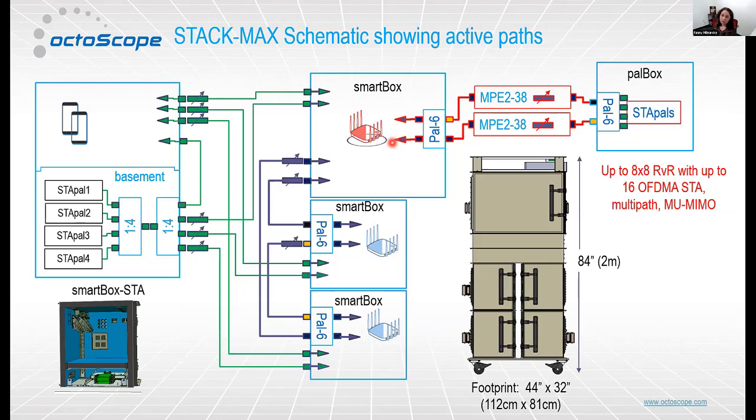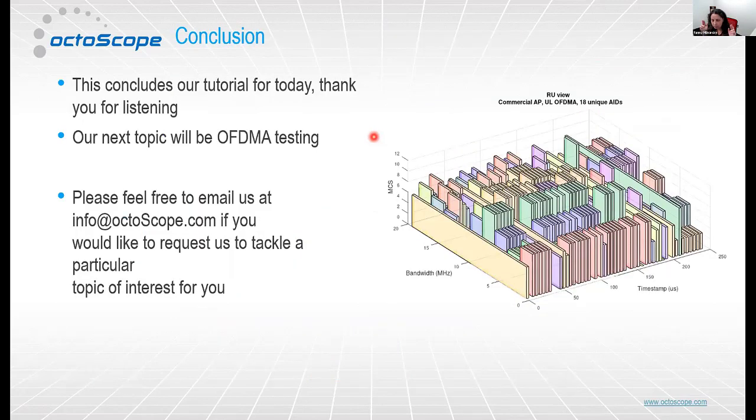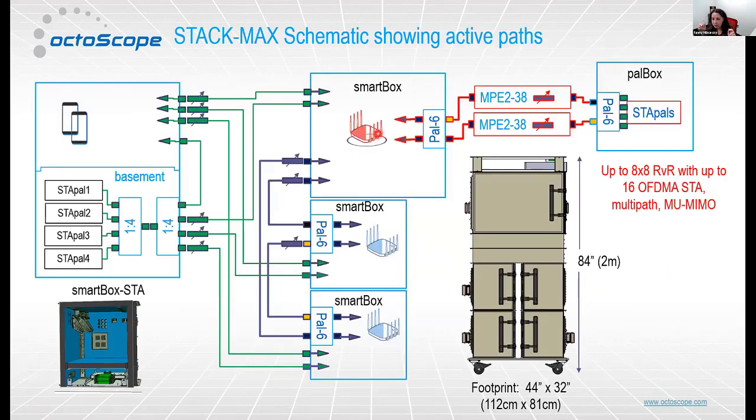It's actually a good question. And last week we did channel modeling, right? And we showed how a typical house model behaves with non-line of sight. So the different floor will just be non-line of sight. And the reflections could come from anywhere and reach the antennas of the device under test. So if you do the IEEE standard model for the house, it does cover different floors and